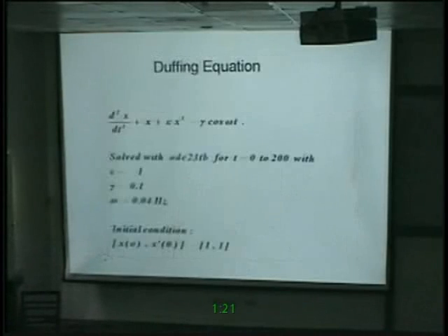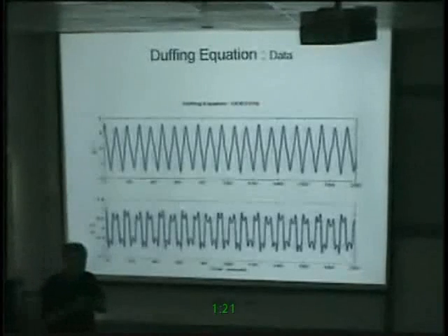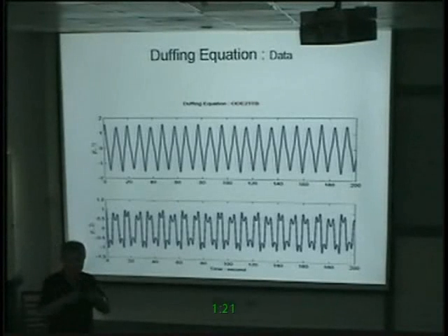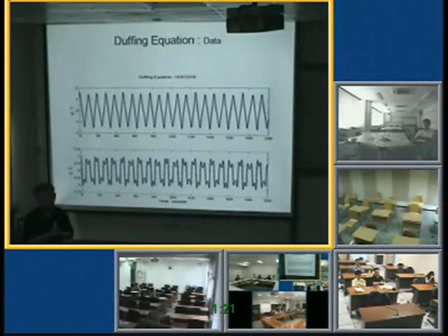Now we come back to the pendulum that we discussed at the beginning. Here, I use epsilon equal to -1. I use gamma equal to 0.1. So this is a force function of gamma cosine omega t. I start from 0 and compute this with the initial condition given here. And what I get is exactly a sharp crest and sharp trough. Why is that? Because with epsilon equal to -1, the pendulum gets shorter and shorter toward the extreme position. So in the extreme position, I move much faster, and near zero, I move more smoothly and slowly. This is a nonlinear pendulum.